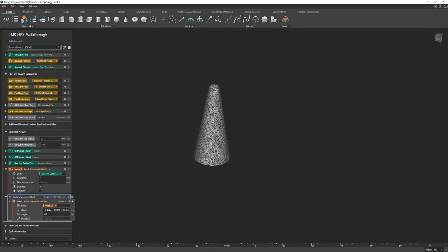We'll divide this by 2. So there's a couple ways that we can call this block. We can do search for divide in here. We can go to the top of the ribbon and select math. Or a newer feature is the context search. I can select in context search. It's going to auto filter all of the options that this block can get nested into. I'll search for divide. I'll pop that into here. And I'm going to put an operand of 2.